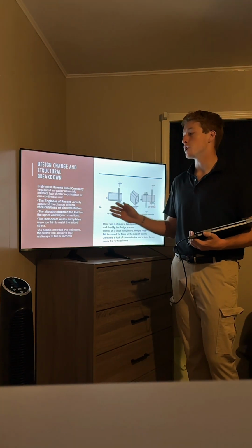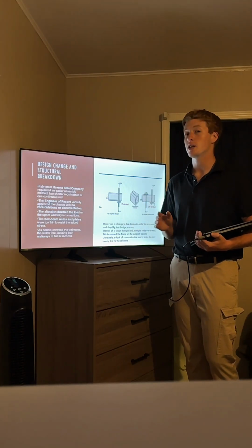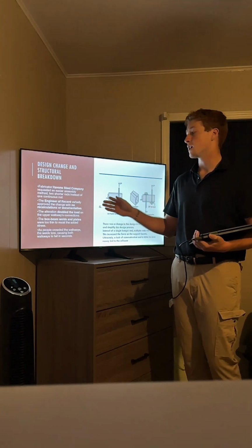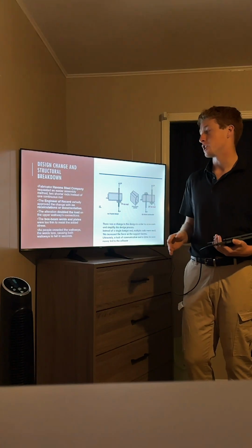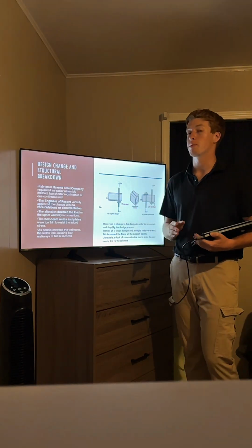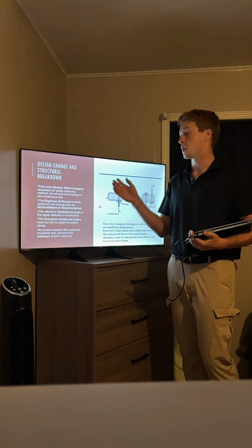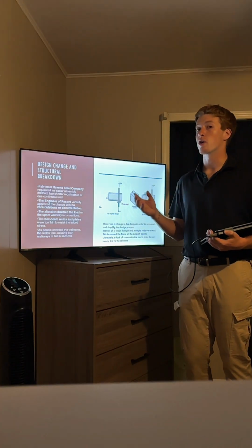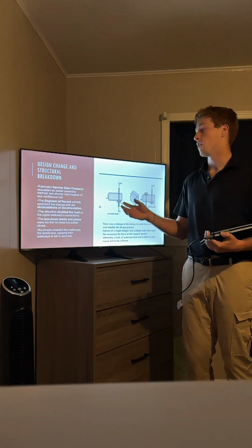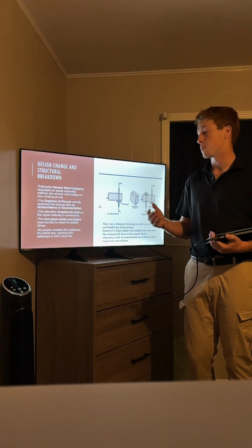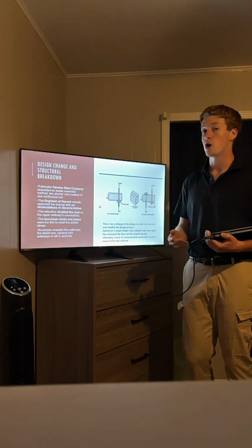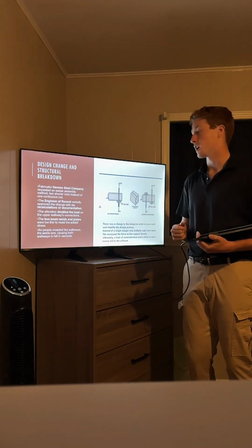This created a huge issue because with no recalculations, they did not take into account that the alteration doubled the load on the walkway's upper connection. So if they're doubling the load, this is where our hazard comes in: not being able to handle what's being built and what's eventually going to be walked on, and the load of people walking.